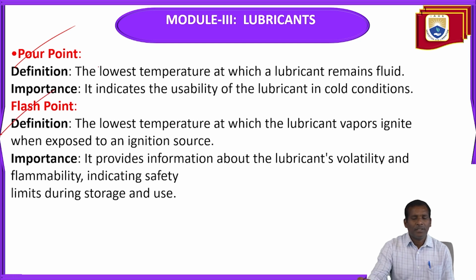Next, flash point. The definition is the lowest temperature at which the lubricant vapors ignite when exposed to an ignition source. The importance is that it provides information about the lubricant's volatility and flammability, indicating safety limits during storage and use.